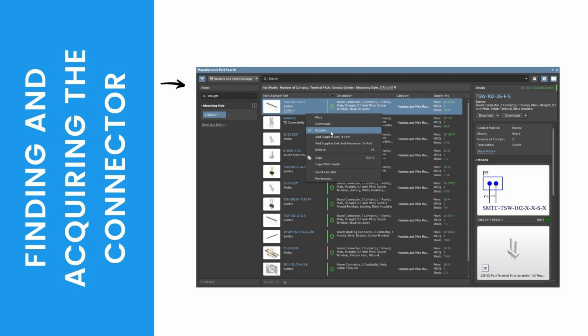Ninth, the single component editor will open. With the chosen data loaded, leave the data values at their defaults and select File, then Save to Server command from the main menus. Lastly, in the Edit Revision for Item dialog that opens, type in a meaningful comment to the component item revision release into the release notes.